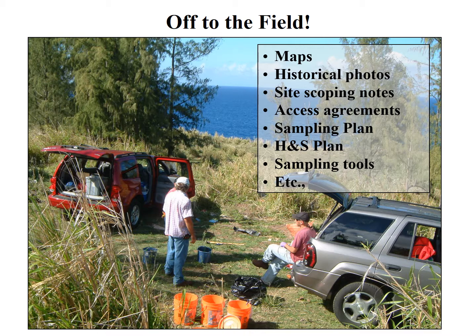And as we have stressed in earlier webinars, initial planning and preparation are very important in designing and implementing good DU-MIS investigations. After gathering any documented historical information pertinent to the site, we start work with a reconnaissance visit to the site to walk the site and review in the field any important historical maps, photos, or other information we have gathered. We also discuss and sketch the location, size, and depth of DUs that will be selected, and identify any site obstacles that may need to be cleared for access to soil in the DUs.